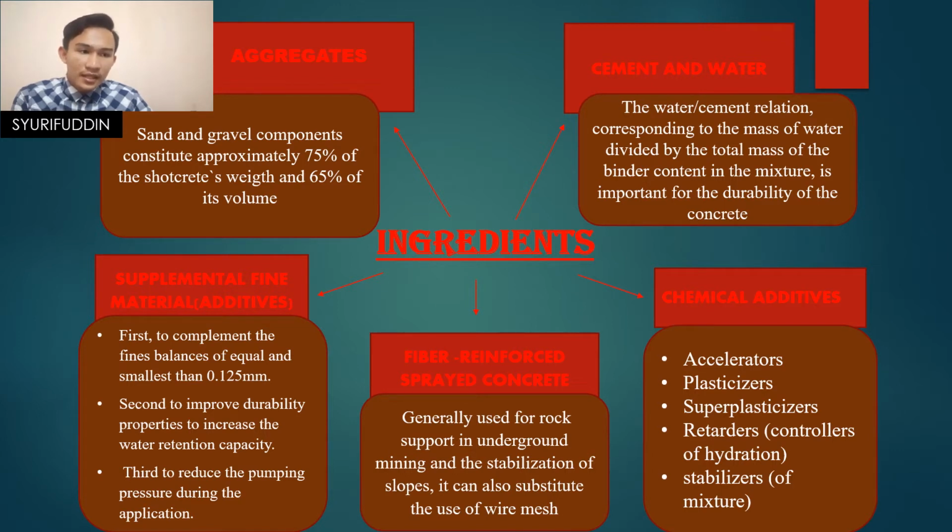Another chemical additive is stabilizers of mixture, which increase the cohesion of the particles, thereby preventing segregation to ensure the pumpability of the mixture.